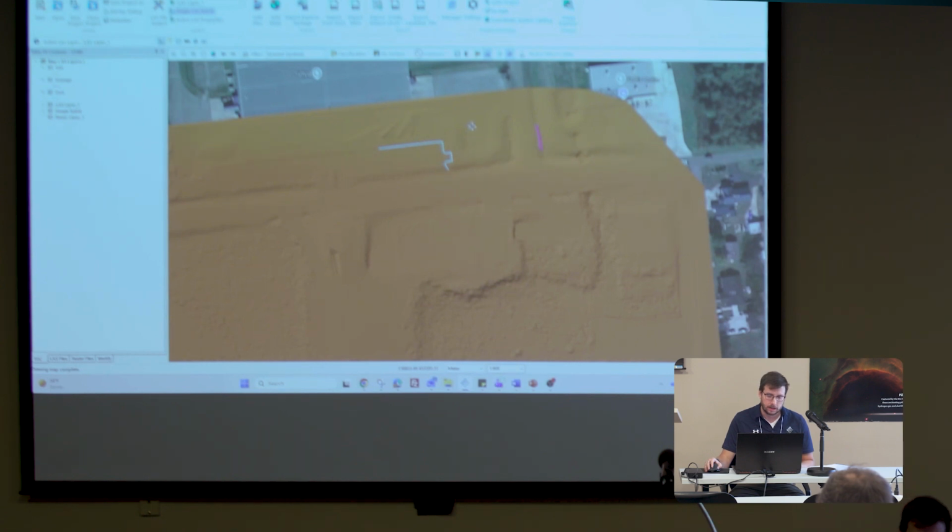Just trying to think of a good example. A lot of times out areas will be on the edge of your project, or maybe you want to leave the water body out. Typically out areas are polygons that you're leaving out, and it wouldn't be points. When we're using break lines in this scenario, they're polylines, and out areas have to do with how you digitize the polygon. An out area could be as simple as you draw a boundary counterclockwise, and you're saying that's the out area, so it's excluding everything outside of that polygon, that kind of thing.